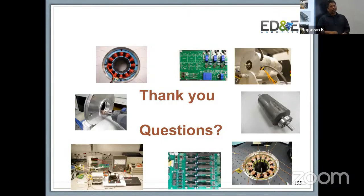So in our case, we had a Hall sensor. The idea was that your motor was working as a sensored motor during startup, and we created a real-time failure in the system. So we actually induced a fault as it was happening. We turned off one of the sensors and said, now can this search coil pick it up?